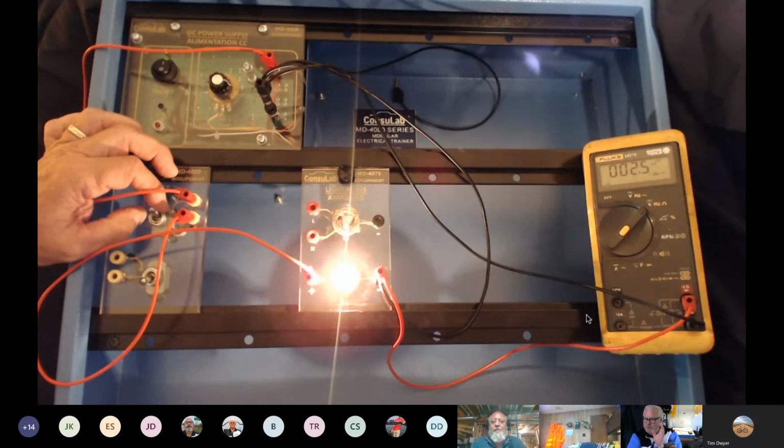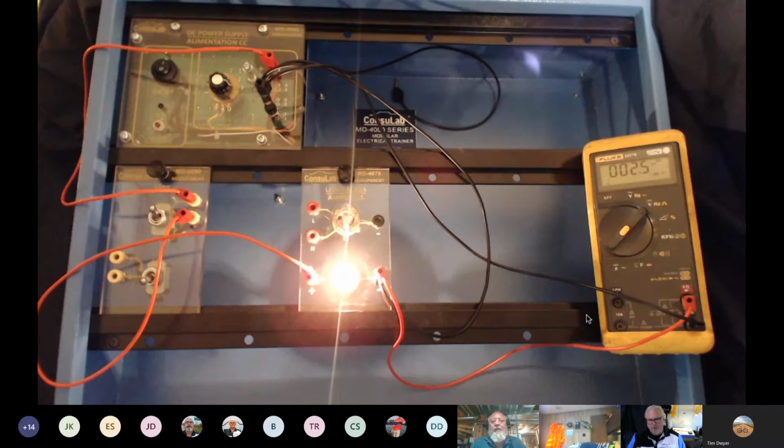I just always want the student to be clear on ground sides, because people disregard the grounds, and we know as technicians and as teachers that we need to stop that behavior right now because it's going to get you. And the coolest part about this is this test will show you, when you get a certain reading on the ground side, it's like an alarm. It's where your problem is.